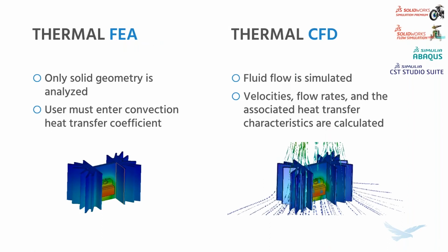A lot of you may know that there are two main approaches in simulation for taking care of a thermal problem. One is to use an FEA tool, and the other is to use a fluid analysis tool. Typically, for the thermal side of things, the fluid tool is going to do a better job anytime convection is involved. In the FEA approach, only solid geometry can be analyzed. We can't actually model the fluid. And so we're guessing or representing with some pretty big assumptions what that convection is going to look like on the surface with a convection heat transfer coefficient.